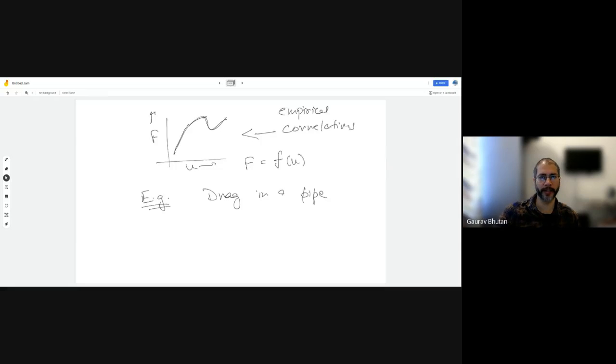So you have to have a pump that is connected to feed in the energy that is getting lost because of that friction. Of course, this energy will heat up the liquid, but as an engineer, you have to figure out how big the pump has to be so that you can deliver a given volume flow rate at the outlet of the pipe.